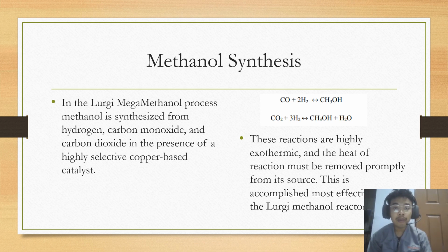The equation for methanol synthesis is CO + 2H2 = CH3OH, or CO2 + 3H2 = CH3OH + H2O. These reactions are highly exothermic, and the heat of reaction must be removed promptly from its source. This is accomplished most effectively in the Lurgi methanol reactor.